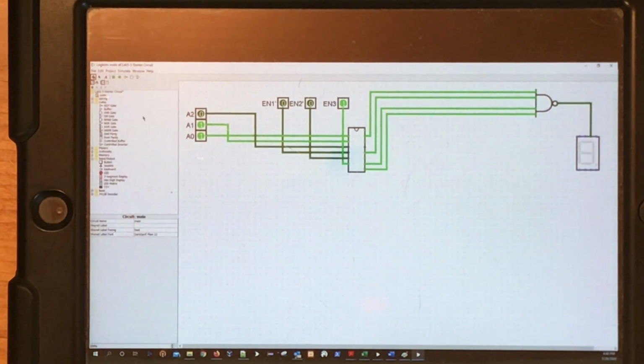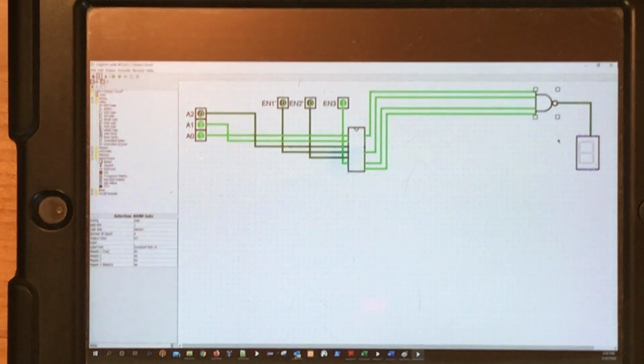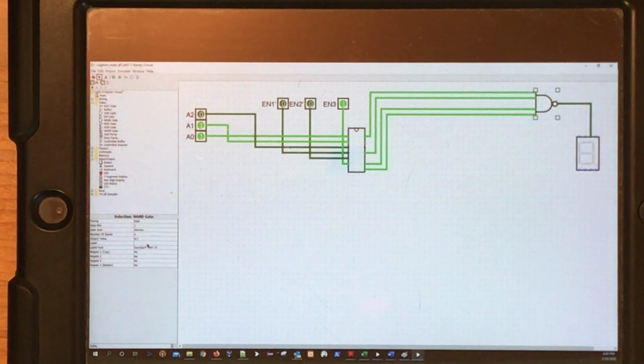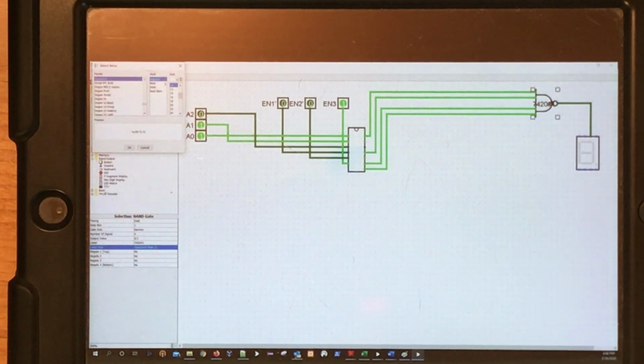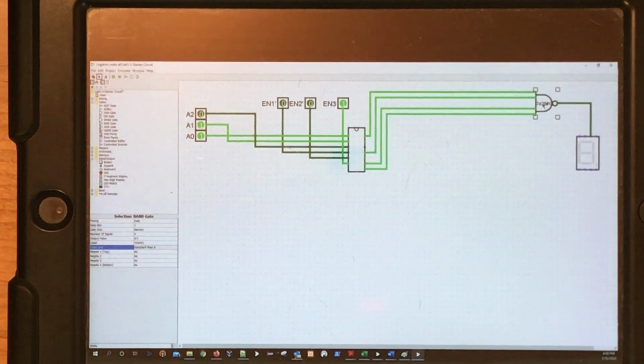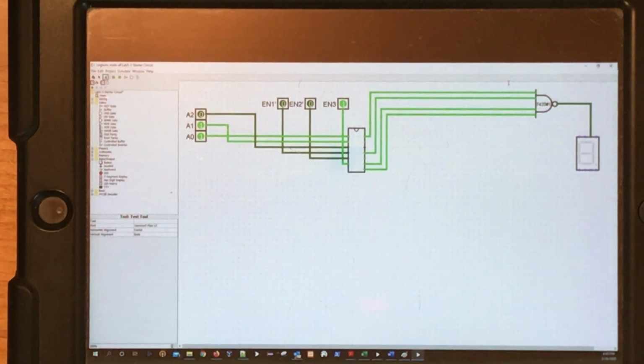Like I said, everything has to be labeled, so this I'll label here. And this is a 4 input, so it's 7420, number 1. Now that's big, so let's change the font size. And that fits inside. That's good. And now I'll put a text here. What pin is this? So I've got to pull up my lab guide, or we can look at Appendix D in your book.